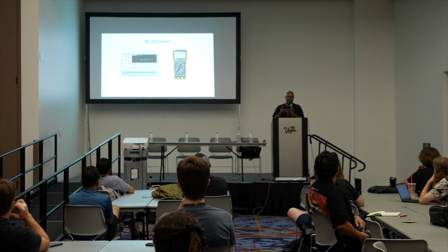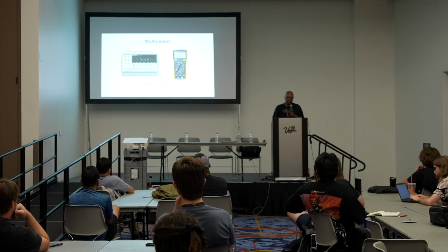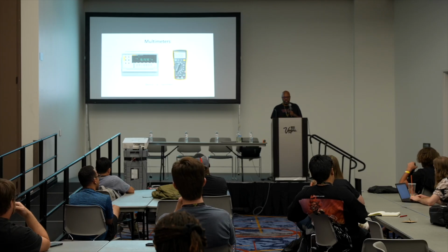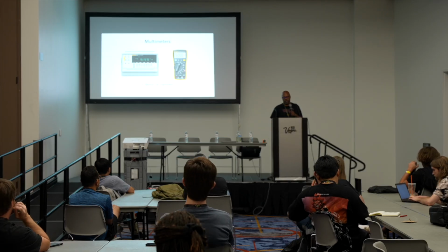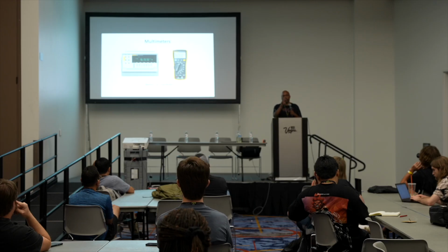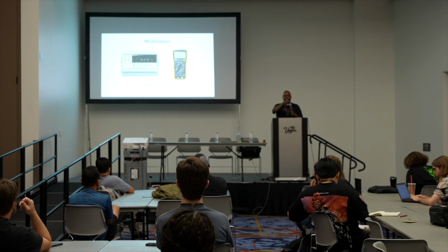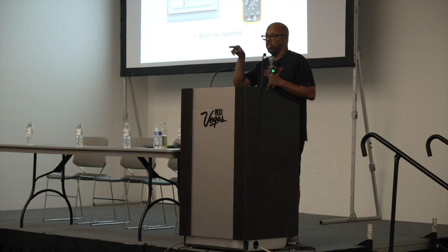One way is with multimeters. So the first thing you always have to have. You gave some out, Sydney, yesterday, right? A multimeter is just a little, you get a handheld one or a bench one. And basically it tells you the voltage between two points. So you can tell if something is high or low. It can read the current, how much current's going through there if you need to know. It can read resistance between two points. It can read connectivity.